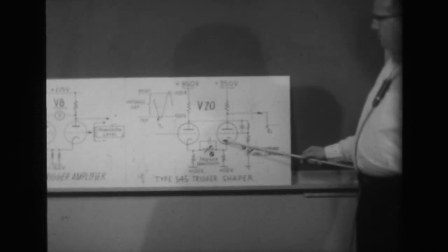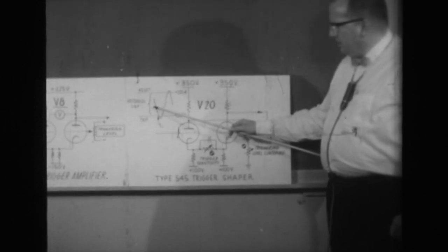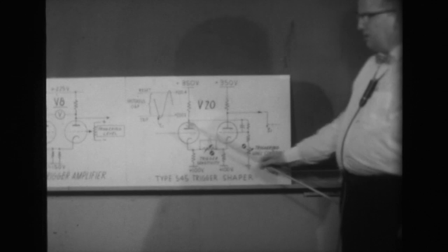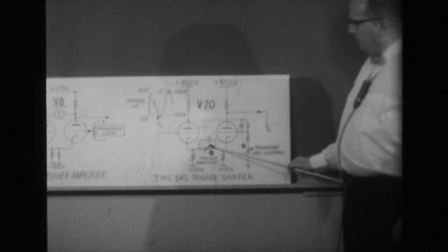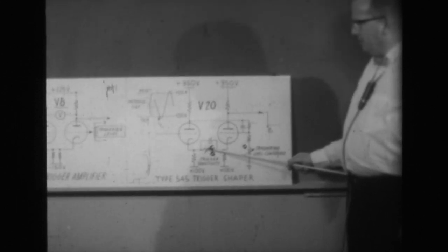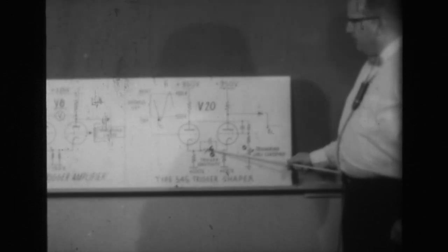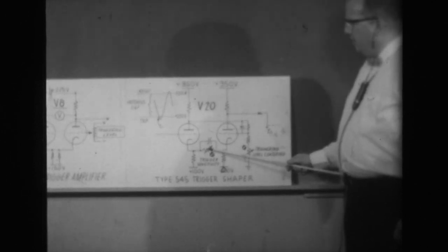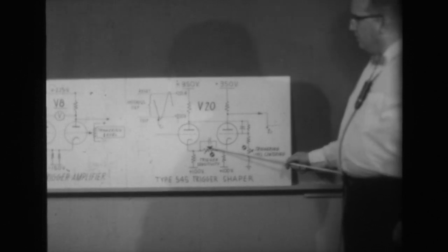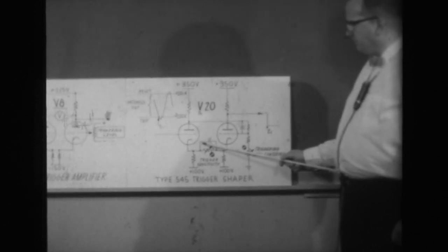If we found that the 100 millivolt square wave did drive through both the reset and the trip level, in other words, did produce a continuous trace on the cathode ray tube, we then backed off on the adjustment, turned counterclockwise the trigger sensitivity pot until a 100 millivolt square wave will no longer cause a smooth trace to be developed, or a continuous trace to be developed on the cathode ray tube.